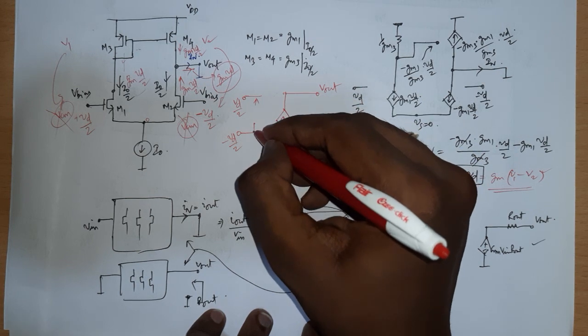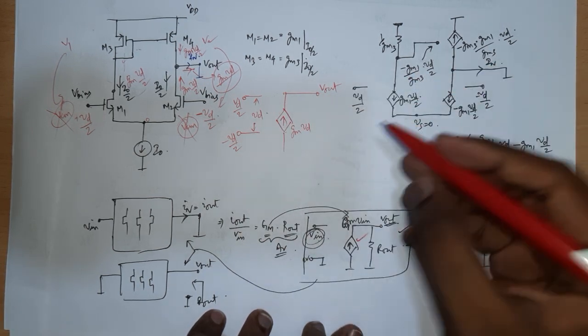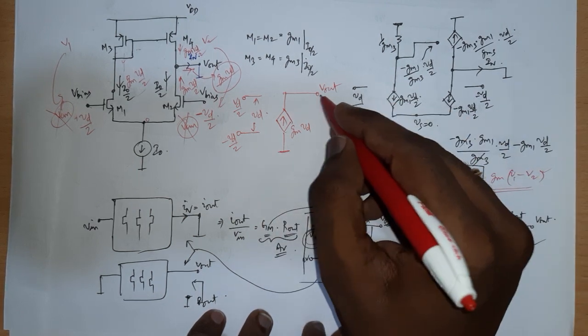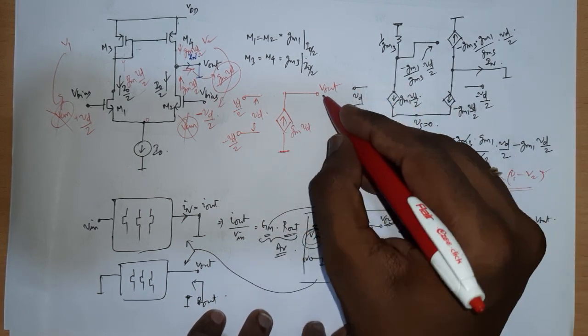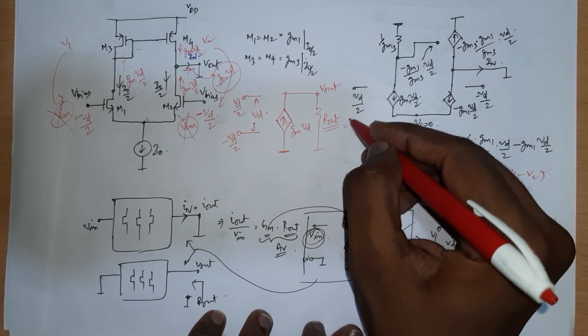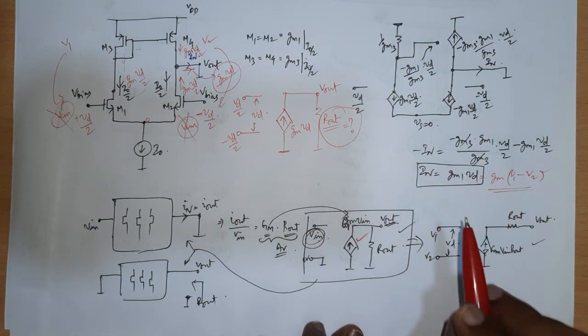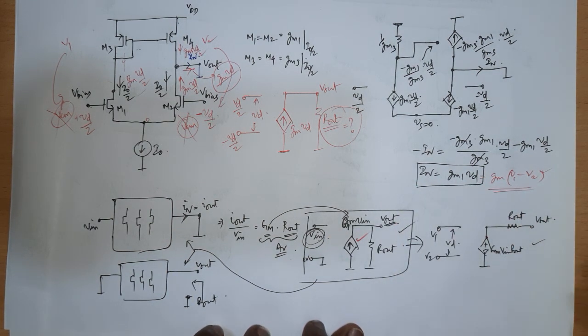The difference is VD by 2 minus minus VD by 2, which is going to be VD. Okay, so half the work is done. We just have to figure out what the output resistance Rout is. Once we are done, our incremental equivalent is also done, and figuring out Rout we'll do in the next class. Okay.